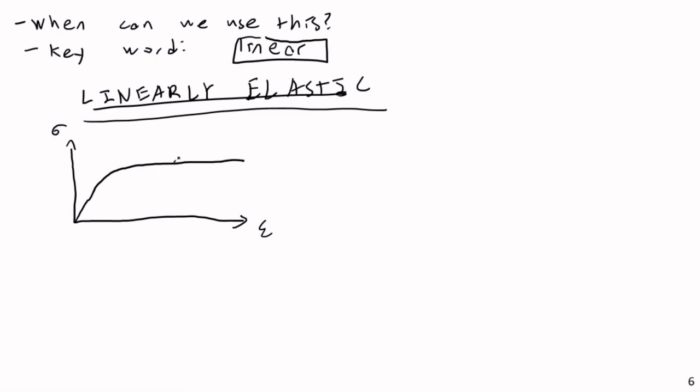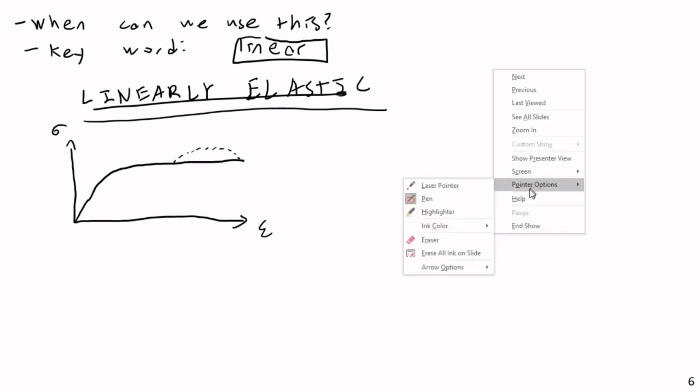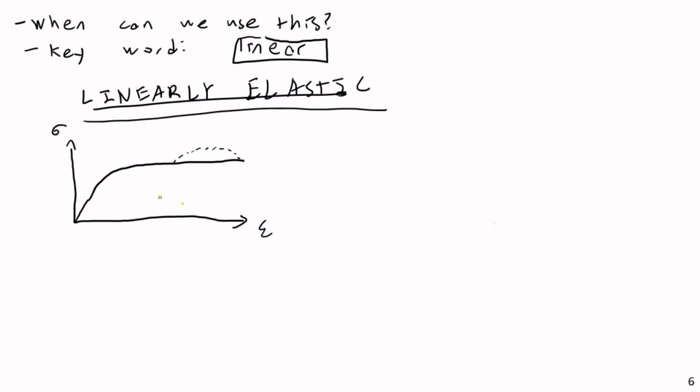In truth, we do get some strain hardening before fracture, but usually for analysis or for design, we just say, okay, let's just consider it yielding at the constant yield stress indefinitely. But anyway, that doesn't matter for this particular discussion. What does matter is that we are keeping ourselves not just in the elastic zone, but in the linear elastic zone. So we are below epsilon yield.